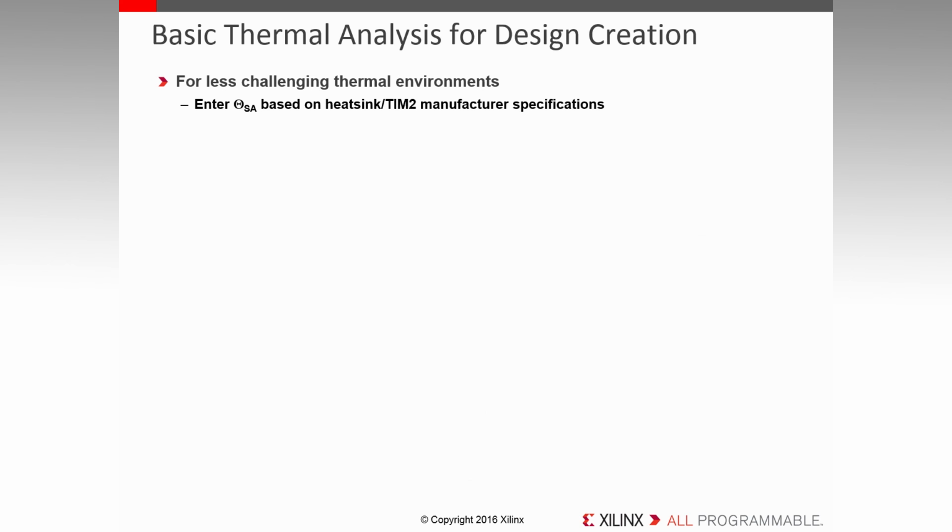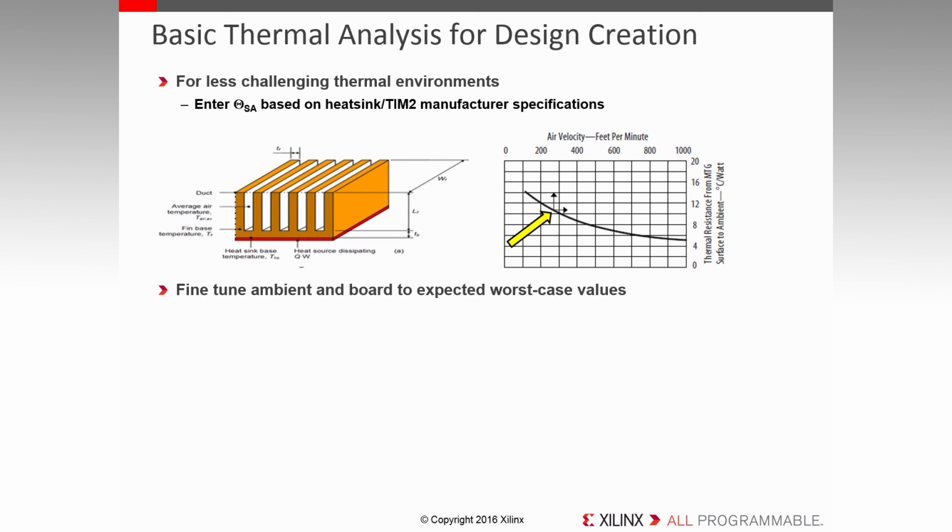Proper thermal design generally depends on the heatsink utilized, the airflow and the thermal interface material used to enable efficient transfer of the power dissipated by the device to the heatsink. XPE enables our customers with basic thermal analysis for less challenging thermal environments. This is the simplest approach to quickly assess the thermal margin with the current thermal solutions. So you could just read the manufacturing spec of the heatsink and thermal interface material and feed them into XPE. For example, assuming 250 LFM airflow, the thermal resistance of the heatsink is 10 C per watt from the manufacturer's specification.